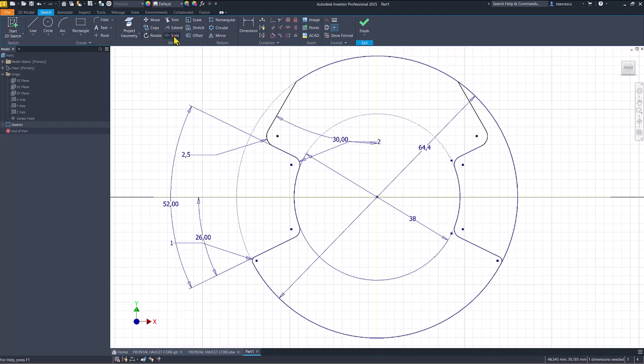We apply split again by cutting in this point and in this point the circle, and we make this. You see, I use this to select this arc. If I start from left to right, we don't select anything, but here I select three entities, 1, 2, 3.